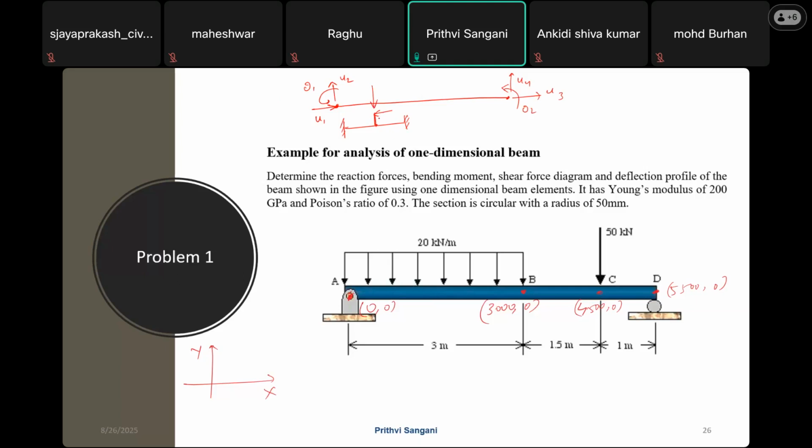So in this case, what happens is that the forces also transfer in this. I'm just doing a force translation and moment translation. So you have forces at this part, and this will be acting here again, and because of this, you will get some moment over here. Because of this force, it is going to resist these axial forces also. So beams will also take axial forces.